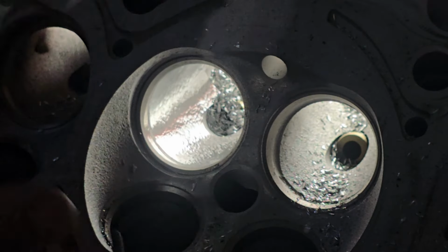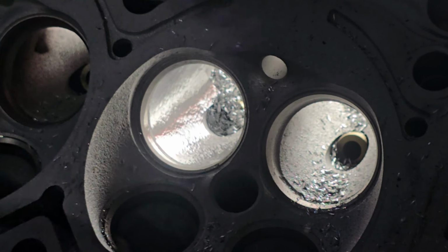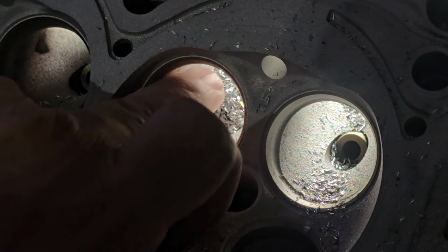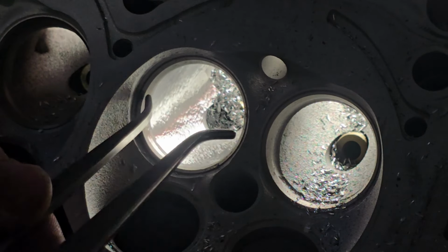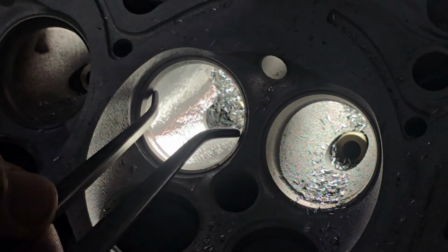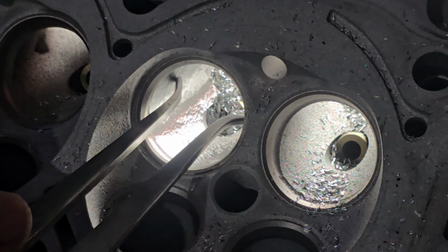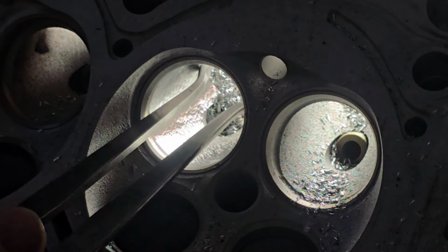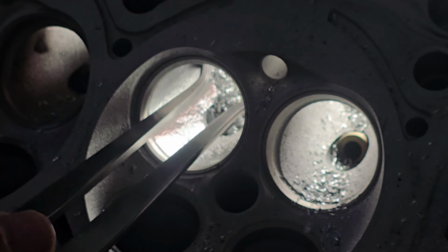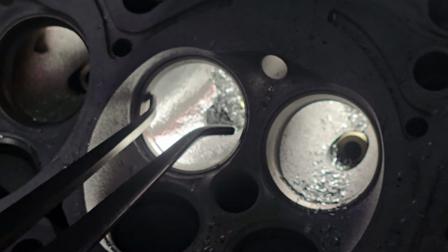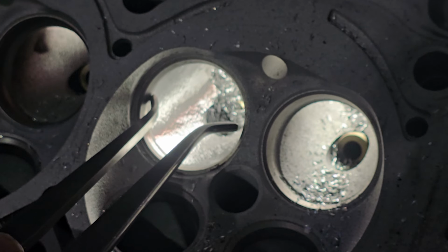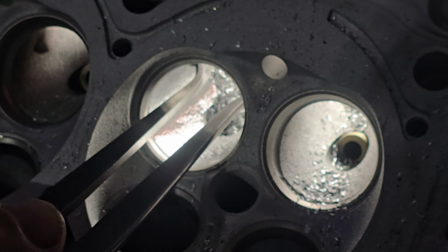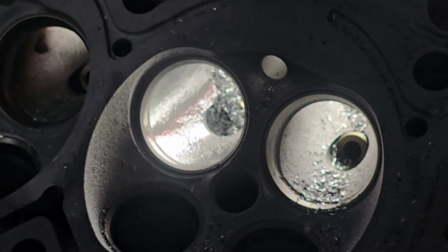You can see you definitely want to use calipers with these Audi heads especially. What we're trying to do is get these walls parallel to the seat and back. So if I come into the seat, that's roughly it, and push it in, you can see it tightens up about there and it only gets tighter. So if I set it at that, okay, we're just loose now, yep, and come back to the seat, you can see we've got about 1.5 mil, 60 thousandths tighter just up in there. So we need to address that.